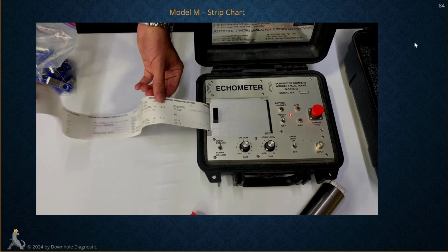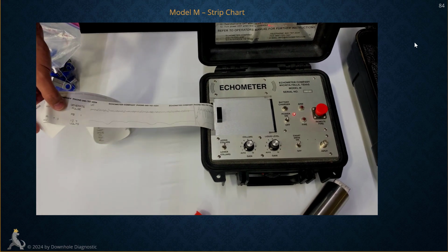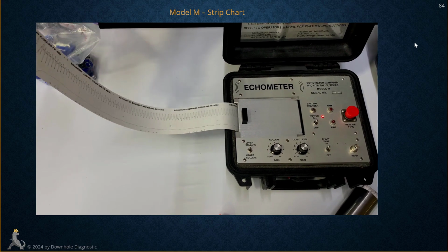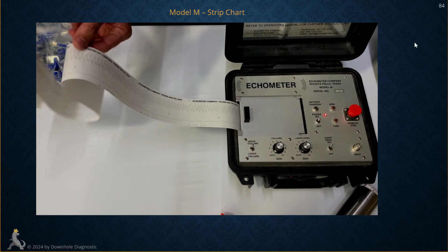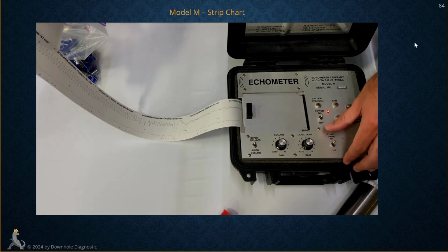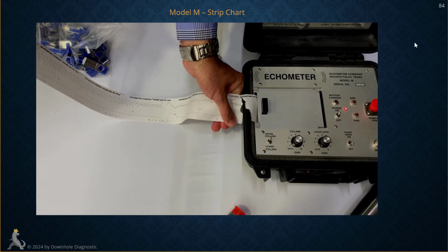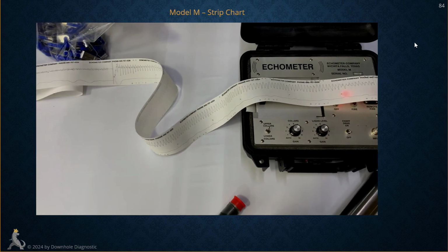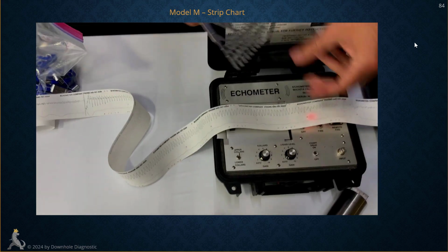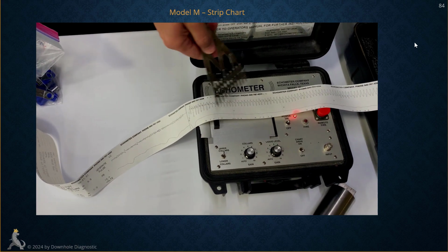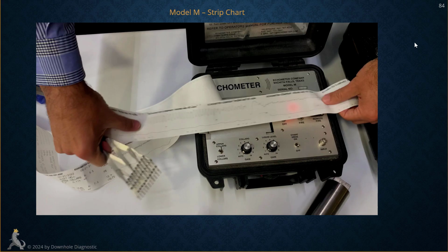Now the software is listening to the well and taking a shot, and that's a shot, and we see the colors. This well is kind of deep, so the fluid level will be deep, over 5,000 feet, and that's a liquid level right there. All right, and you've got an 11-point divider you can use here? Yes, we have an 11-point divider, and you should spread this paper all over your table, start counting colors here, all the way down to the liquid level.